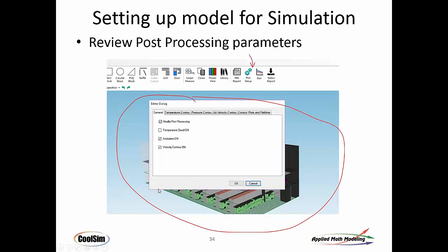So setting up a post, as I mentioned, the way this system works is you run a post-processing script on the cluster. That's part of the sequence for CoolSim, and we do that intentionally so that A, there's consistency about what's being run, and B, you don't have to spend a lot of time doing it manually. Most CFD analysis systems require you to post manually, where you're creating each image manually and setting it up and redoing it. And when you're driving to optimize a particular design, that's tedious.